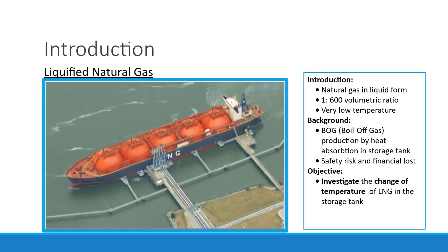There are two common types of LNG tank. First one is the flat bottom tank that usually possesses large capacity. And second one is the VIT or vacuum insulated tank, which is a pressurized tank around 2 bar, though its capacity is restrained to small.